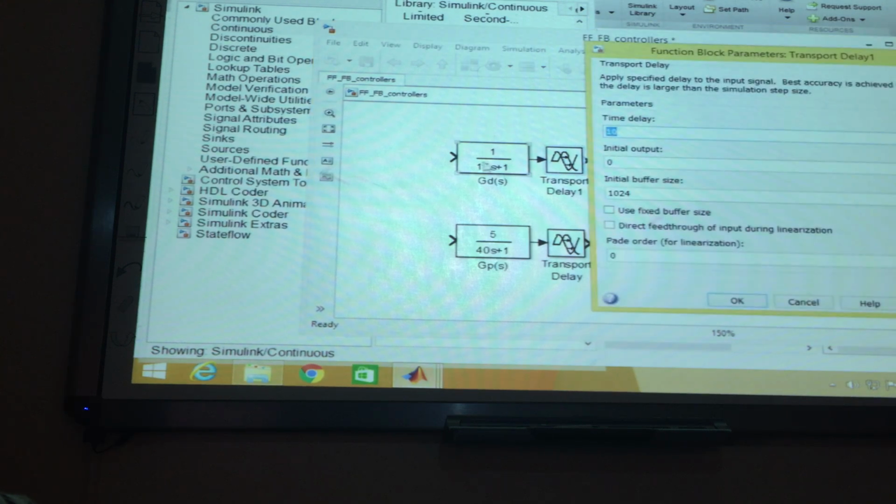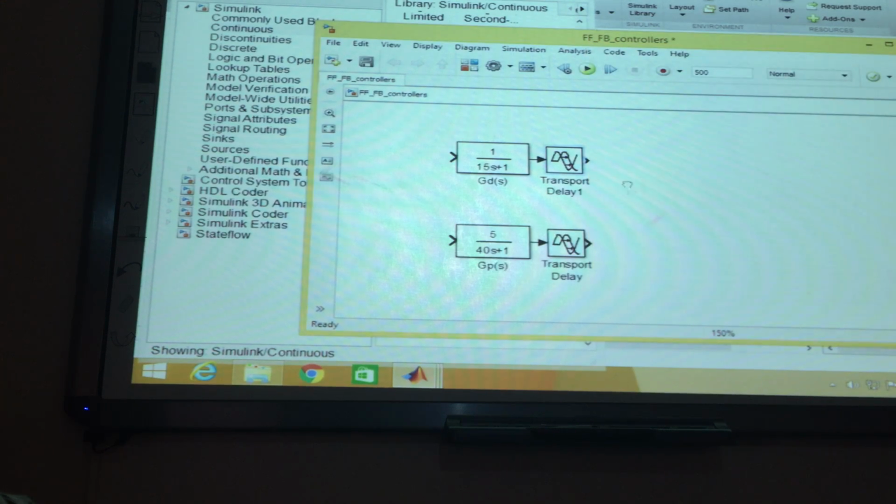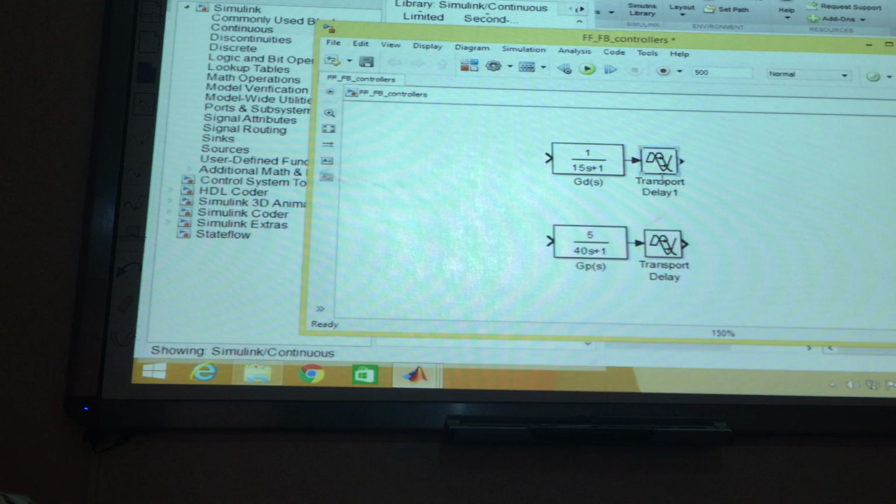The transport delay is going to give you the response, how it will look. And this one should be more. Let's take it 20 seconds, just for example. If you would like, you can write this one down, like exponential minus 20 s. And we can copy and paste it over here as well. This is 10s, right? Is it okay, guys? This is going to be a label.